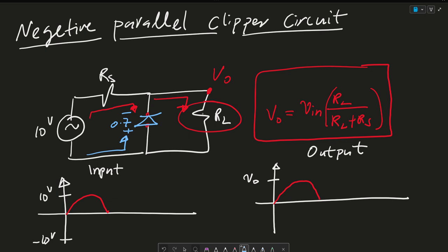So my current isn't going to want to flow through this resistor, but through this short circuit and follow the loop. As a result, since this is 0.7 from A to B, this is also going to be 0.7 from this A to this B. So the drop across the resistor drops down to this 0.7 and comes back up.